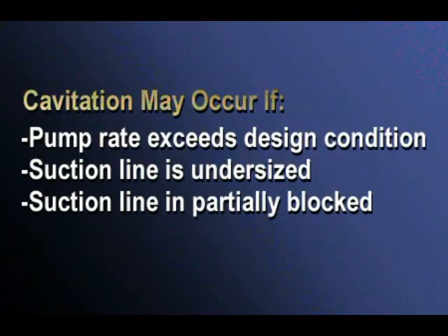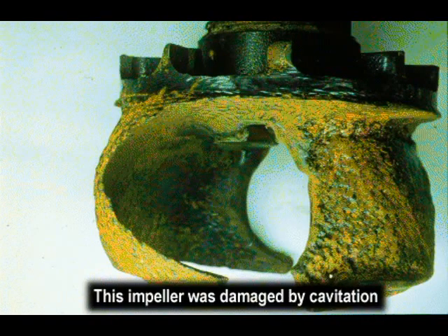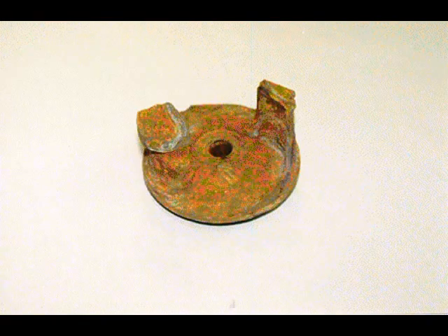When a centrifugal pump operates under these conditions, an area of very low pressure can form around the impeller. If pressure falls below water vapor pressure, then vapor bubbles can form in the water. As the water moves through the pump, the pressure increases, which causes bubbles to suddenly collapse with enough force to actually gouge small pieces out of the impeller. The formation and collapse of these bubbles is called cavitation. Cavitation can also be caused by the action of the edges of the impeller.